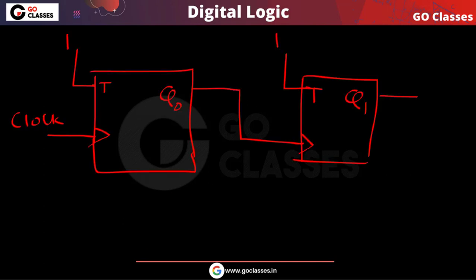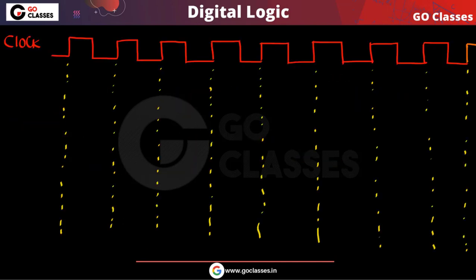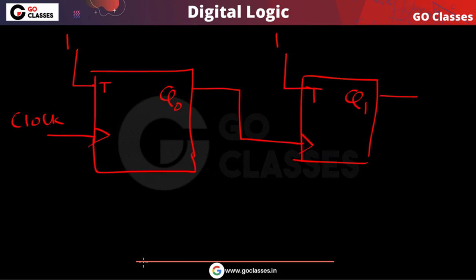So this is your circuit. Now in this circuit, let's assume this is the clock. Then what will be the output waveform of Q0? Let's assume that initially Q0, Q1 are both 0 0. Now one thing you should notice is that this is a positive edge triggered T flip-flop, and this is also a positive edge triggered T flip-flop. So whenever this clock goes from 0 to 1,